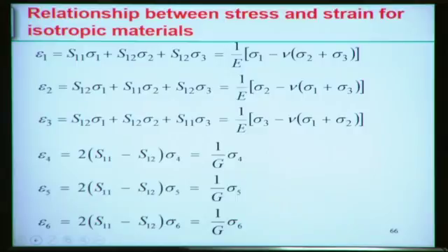Now if we reinvestigate these things in terms of the compliance terms, in the linear system of equations, epsilon 1 is S11 sigma 1, plus S12 sigma 2, plus S12 sigma 3.